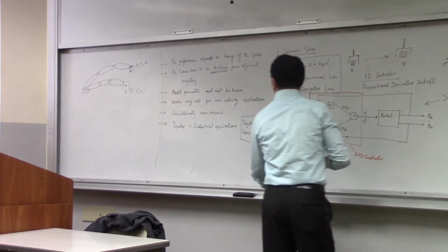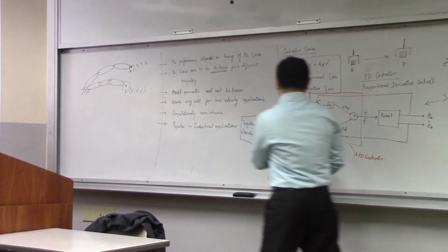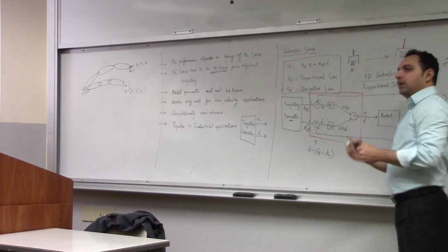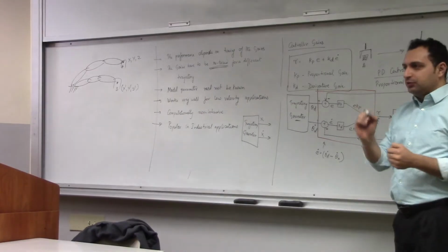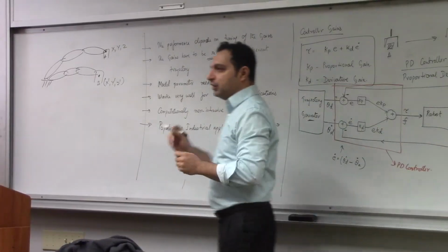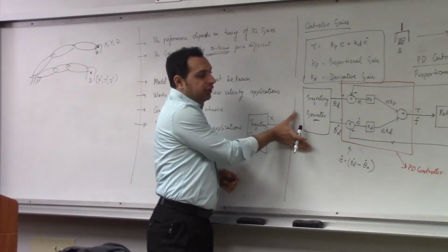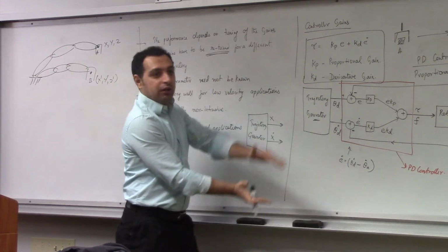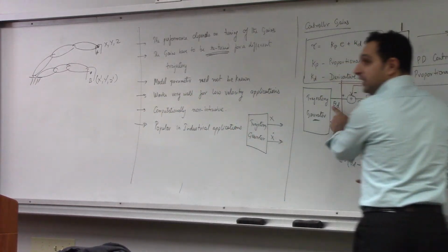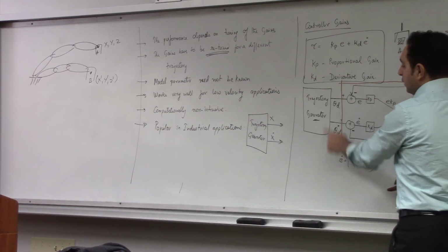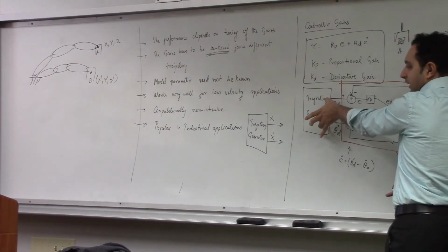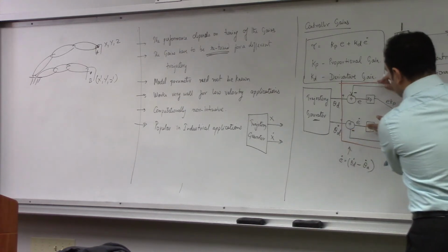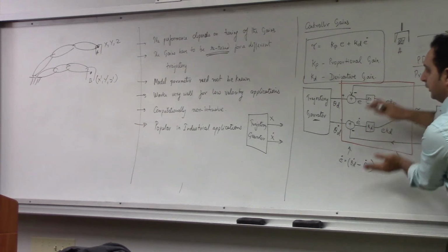Now, what I'm asking is the following. Previously, we had a trajectory in Q dot. That's understandable because when I move a joint, the joint displacement changes. If we are doing independent joint control, we have to tackle each joint separately. So if you have 3 joints, this controller will be repeated 3 times, once for each joint. For joint 1, this will be theta 1D, theta 1 dot, and so on. For a 3 degree of freedom arm, the generator gives 3 joint angles and 3 joint velocities, and I repeat the same independent controller for each of the joints.